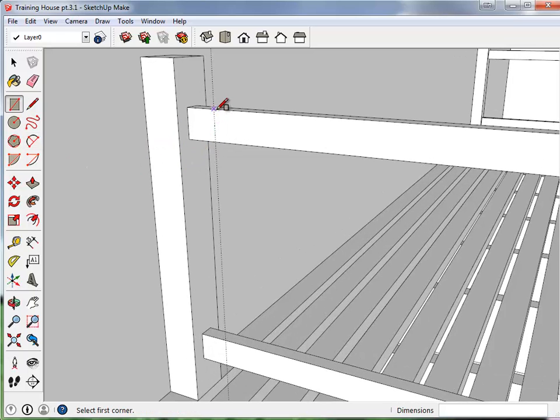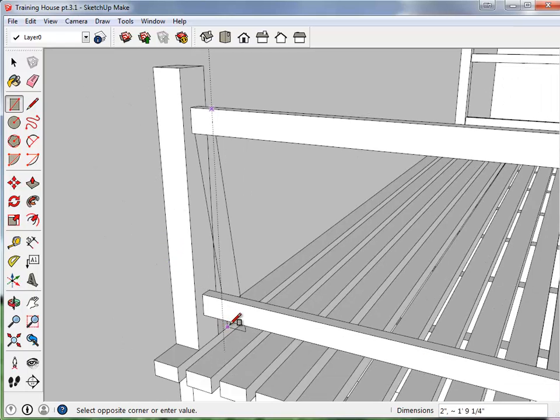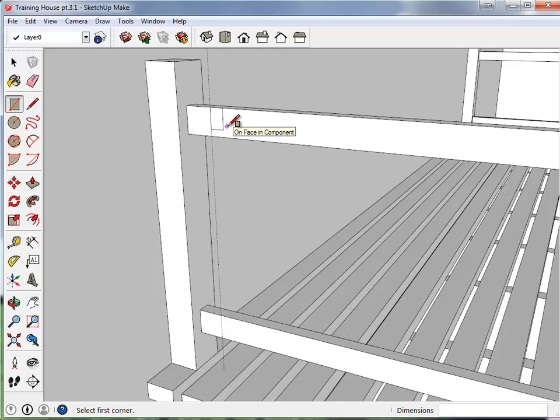Let's create our slats here by snapping the back edge, or the top edge, where the dimension line meets, pulling it down, and we'll use the distance of 1.5 feet, comma, 1 inch for thickness. And there you go.